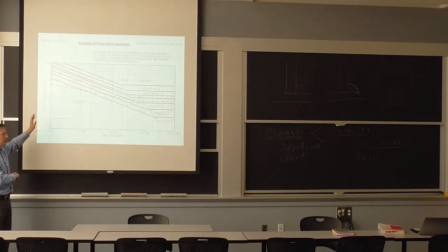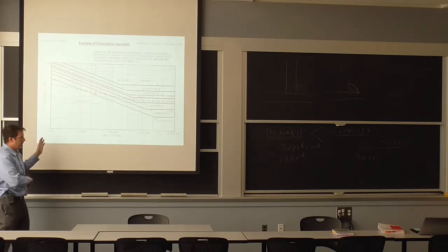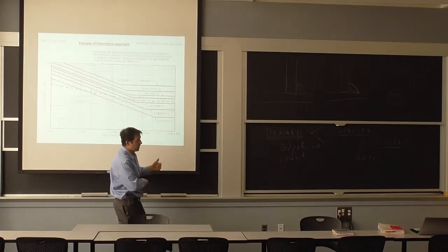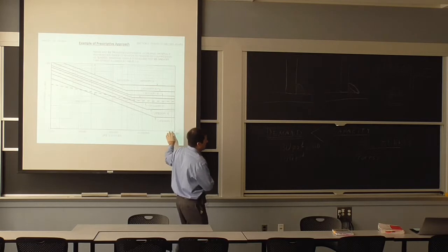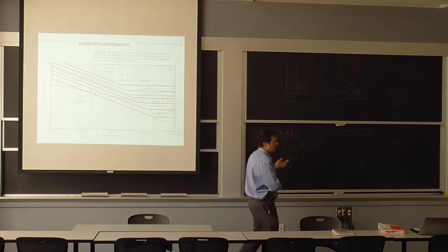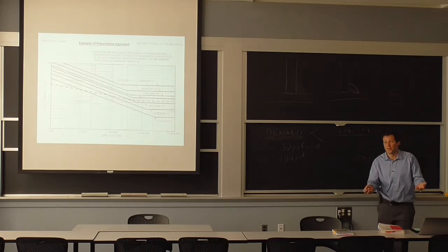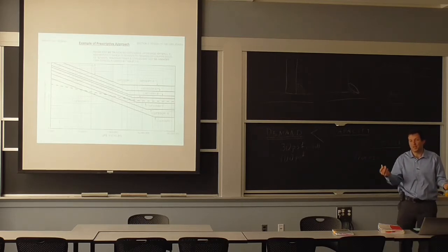So here you can go from minus 50 KSI to plus 50 KSI with steel, and it won't fail. But depending on what you say is going to be the number of cycles, if it's vibration, it's very, very high. If it's takeoff and landing of an aircraft, it's less. If it's going through potholes, your guess is as good as mine, depending on the region you are in this country.